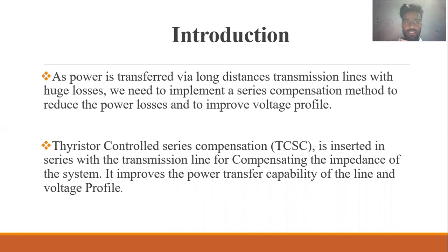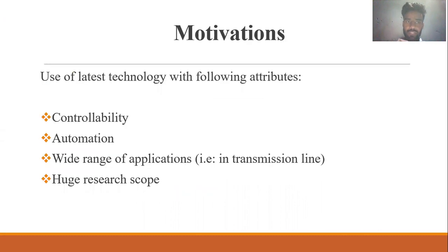In this case, we are inserting a thyristor controlled series compensator, a compensator providing capacitive reactance in series with the transmission line, which compensates impedance and improves voltage profile, power transfer, and power transfer capability. So moving ahead, what is the motivation behind this project?